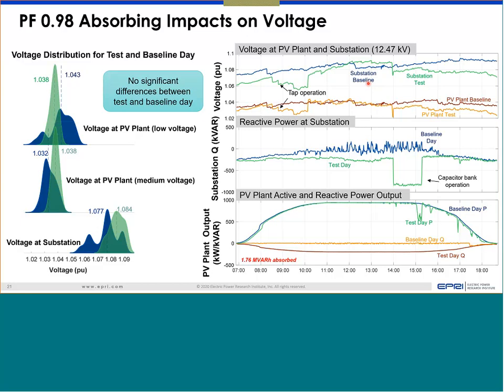But if it fails to detect that, then there is a possibility that it will keep on operating at some higher voltage on the other two phases. And as long as there is load, it will inject current to the system. It will sustain a couple of days. I think we heard that example, that it stayed connected until a utility noticed that.